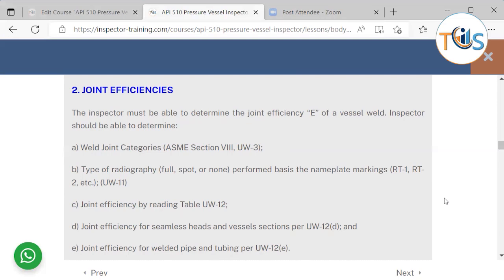You can also see this from the formula calculating the thickness for a certain pressure, that the thickness would be twice for the longitudinal weld because it is experiencing twice the load under the same pressure. So that would be the deciding factor.